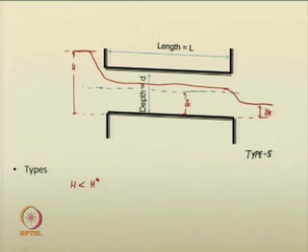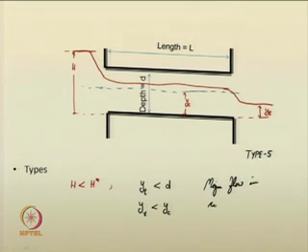So, this depth is critical depth YC. So, you have H less than H star. Now, also you have YT less than D, so hydraulically short, YT is less than the critical depth flow inside the barrel. So, this way the flow inside will be subcritical, major flow in culvert is subcritical, only at the outlet it goes into the supercritical depth YT which is less than the critical depth, right.